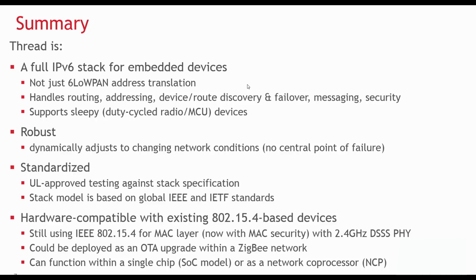Like Silicon Labs' EmberZNet solution for ZigBee Pro, Silicon Labs Thread supports both the single-chip SoC approach, where the full stack and application are linked into a single binary on one chip, and the two-chip network coprocessor, or NCP approach, where the base stack implementation resides on the SoC but functions as a coprocessor via a serial interface to a host MCU running the application layer. This NCP approach is ideal for border routers or other devices where there's a complex system in which Thread plays only a peripheral role.